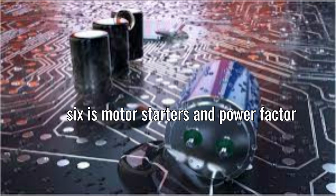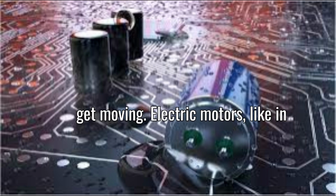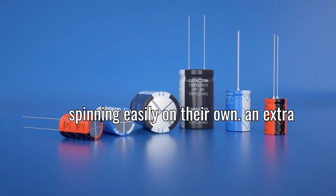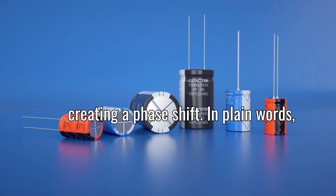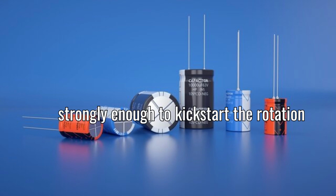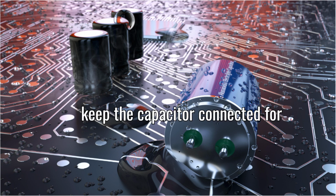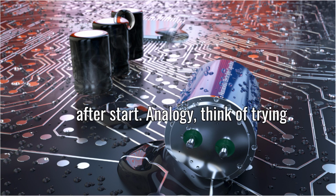Number 6 is motor starters and power factor correction. Motor starters, helping motors get moving. Electric motors, like in fans, pumps, or fridges, don't start spinning easily on their own. They need an extra push. A capacitor gives that push by creating a phase shift. In plain words, it makes the motor's magnetic field twist strongly enough to kickstart the rotation. Once the motor is running, some designs keep the capacitor connected for efficiency, while others disconnect it after the start.